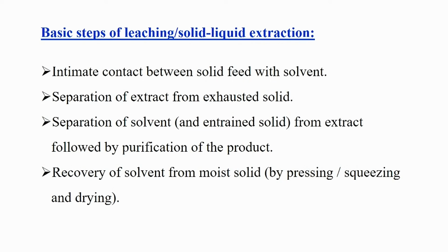First step is intimate contact between the solid feed and the solvent. Here we have the solid and we are adding the liquid. So, the solid is contacted with the liquid. That is why it is solid liquid extraction, and inside this solid, one target component is there which can be solubilized inside this solvent. Then, separation of the extract from the exhausted solid.